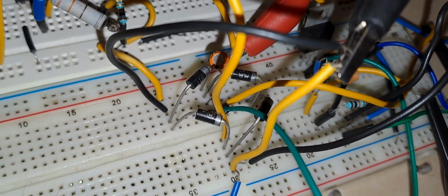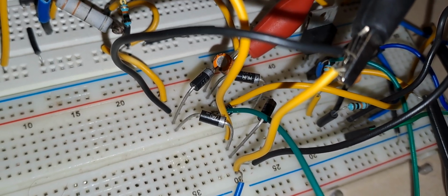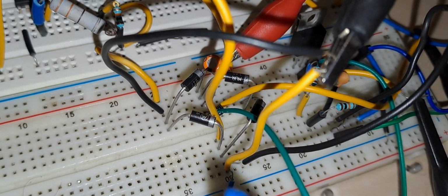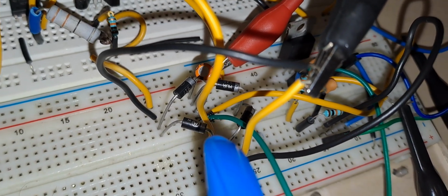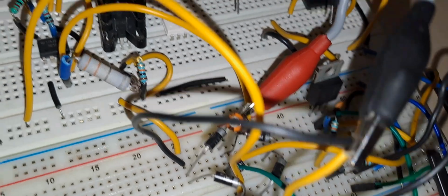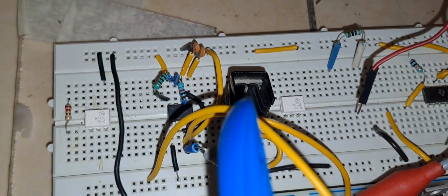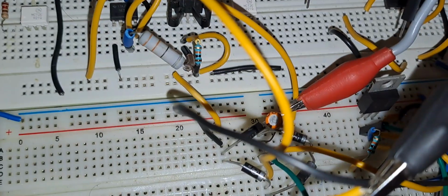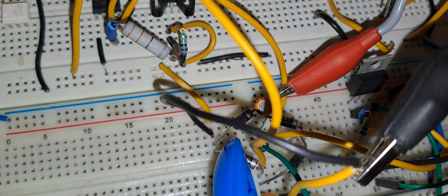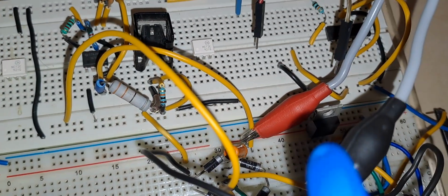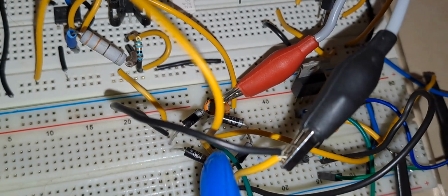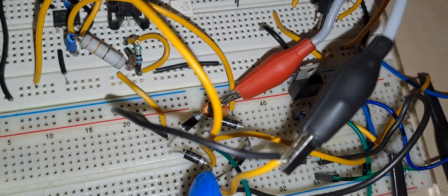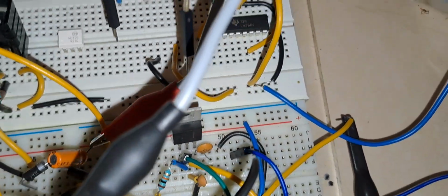I am using Schottky diodes for the purpose. These are high frequency diodes. That's why I am using Schottky diodes, so that the waveform is not clipped off. The 48 kilohertz signal is generated and fed to this ring modulator. Also, the modulating signal from the oscillator is fed to this ring modulator. The complete modulation takes place here and the output is fed to this envelope detector.